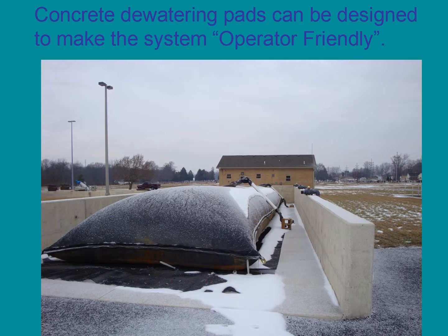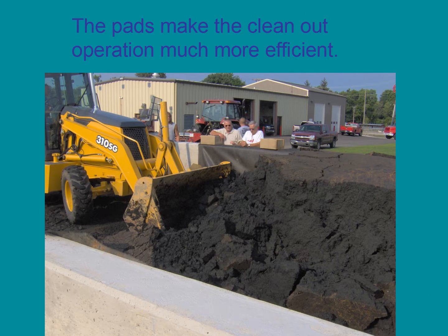Concrete dewatering pads can be designed and constructed to offer the operator many advantages over simply laying out the bags on drying beds. The pads make loading out the solids much easier and less time consuming.